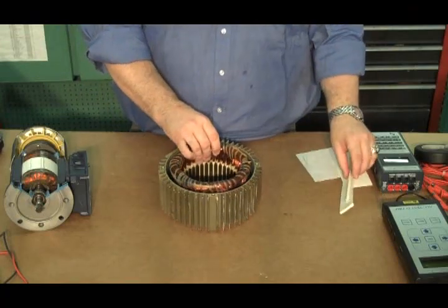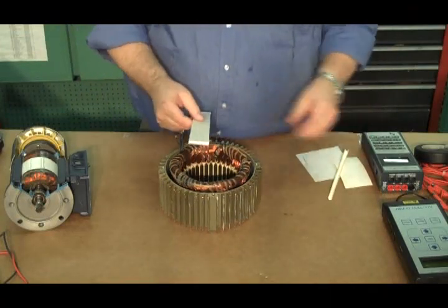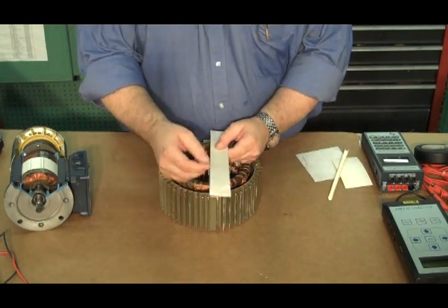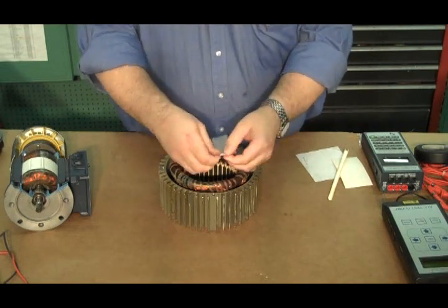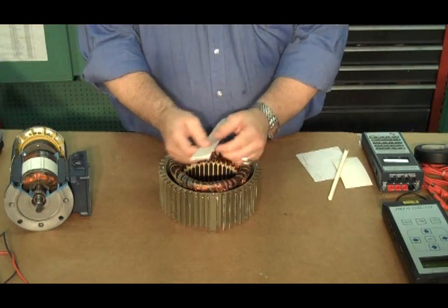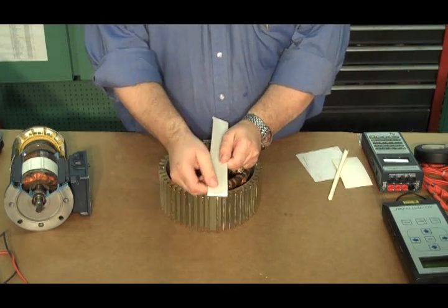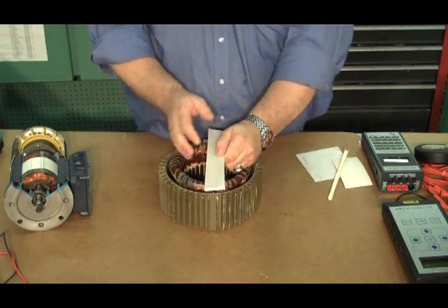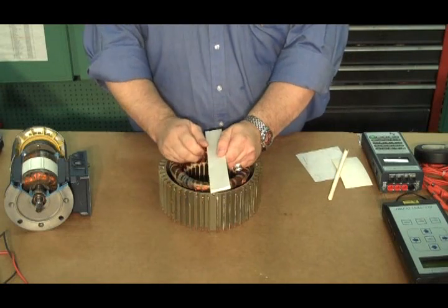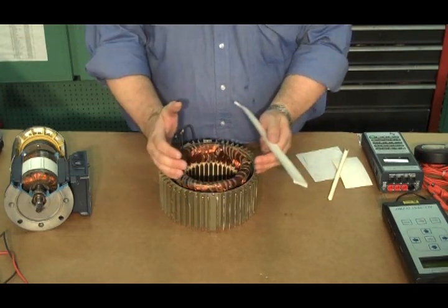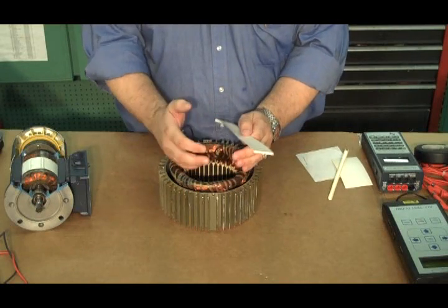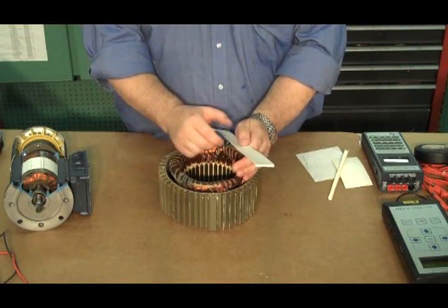The slot liners on most machines nowadays are a Class H Nomex insulation system, which is very, very firm and capable, but it's also very smooth. And the reason it's smooth is this acts as a lubricant for the wire to expand and contract. So whenever this machine starts, the windings want to pull themselves into the motor, move in the slot, and so on.